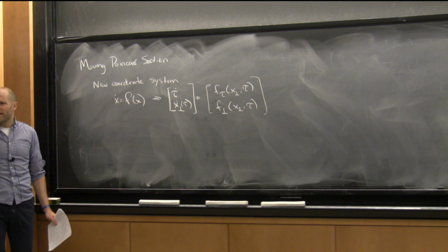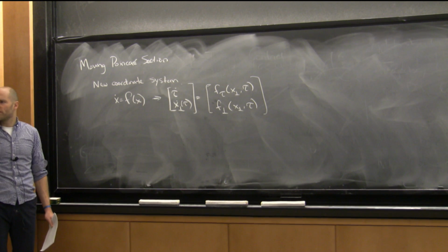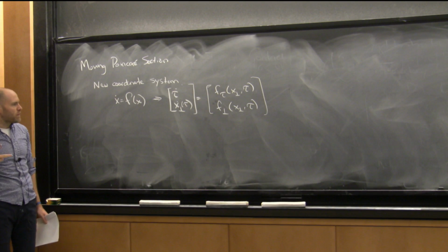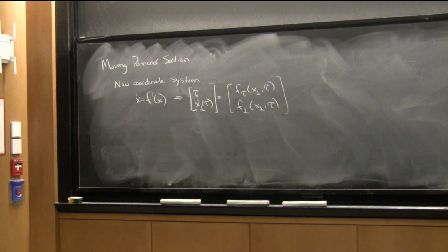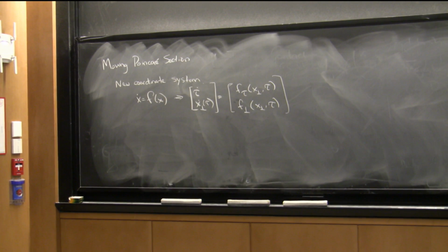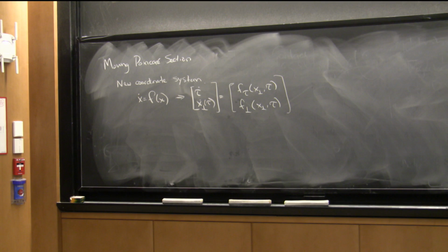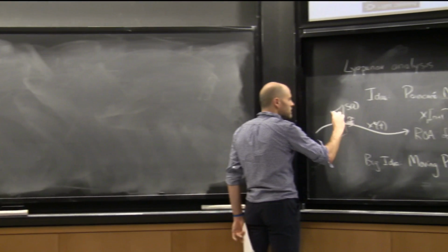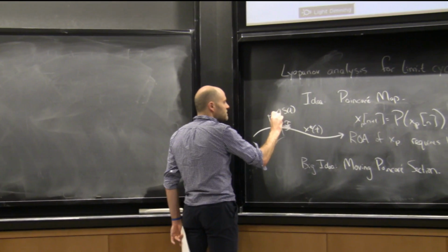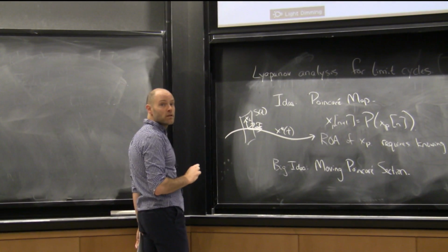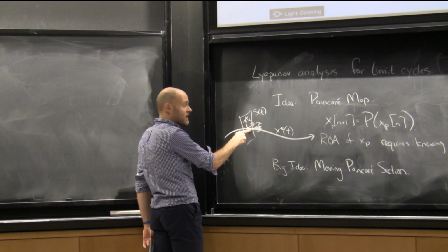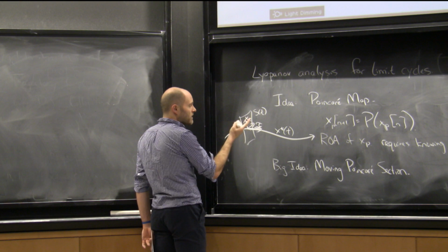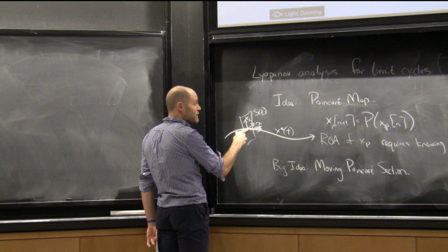Does that make sense? I can always just pick a new coordinate system for my robot and rewrite it in that coordinate system. And the coordinate system I'll pick is I'll call tau the dimension along the trajectory, right? And then as a function of tau, at any given tau, I can define my x-perp coordinate system. So I can always rewrite my state in that coordinate frame, and I can update my dynamics, my flow, on that.